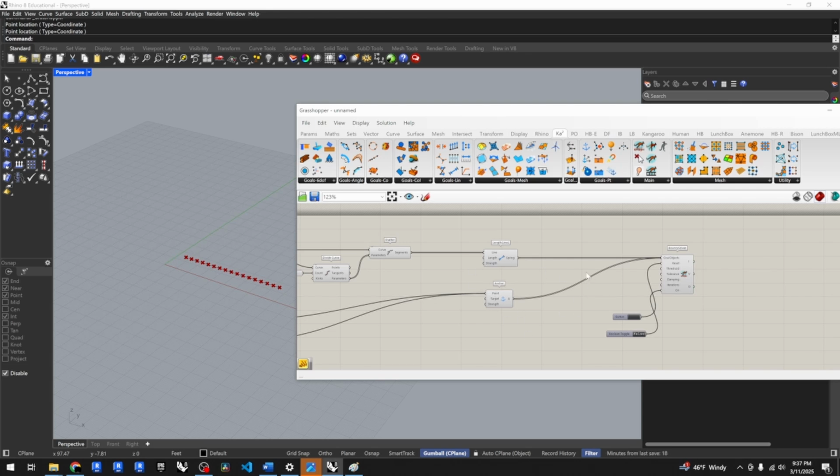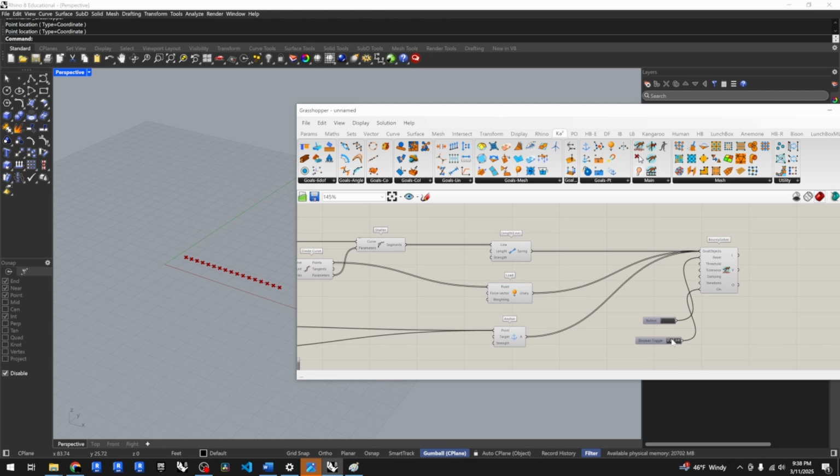And the reason for that is I'm missing the main ingredient. If I'm thinking about this being a line hanging, I actually need to add a load into the equation of my goals. And so the load, or the areas that I want the load to be acted upon, are all of the little points in between my line. And then I want to add this into my goal objects. So then when I set the solver to true, I can see I get an arch.